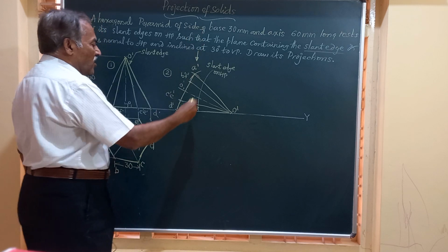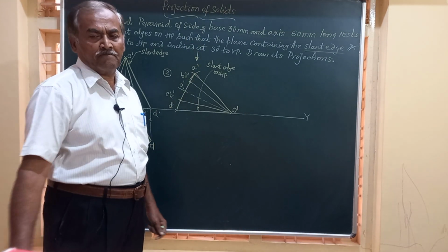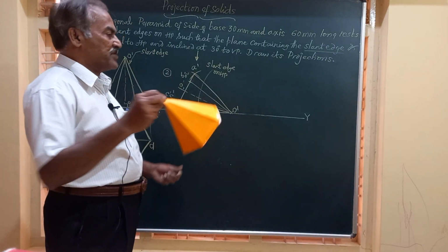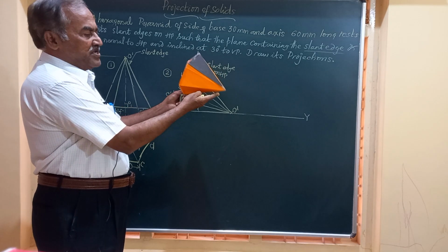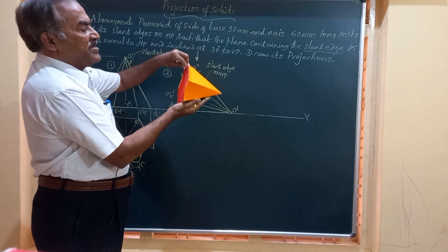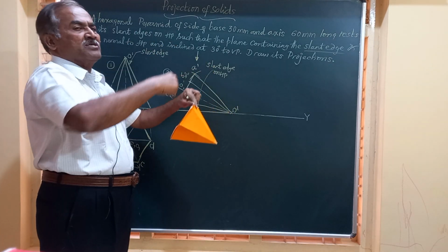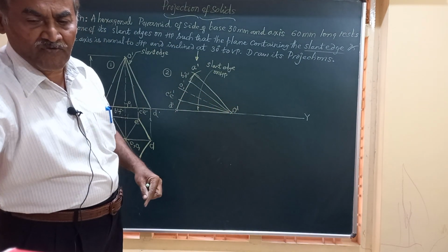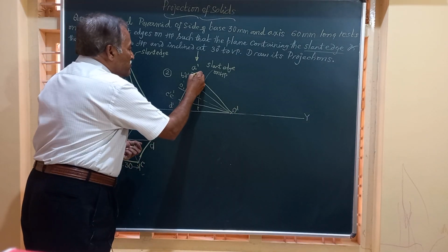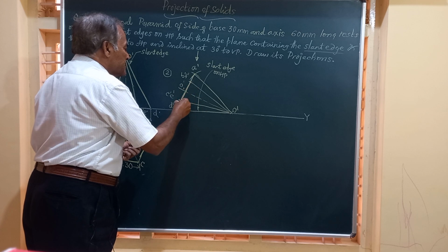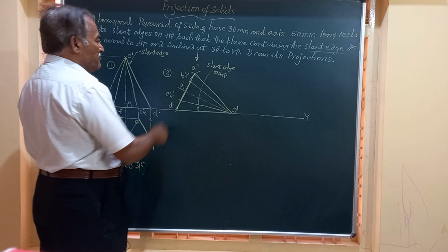and see how we view this solid. So friends, remember, whenever any of these pyramids rest on one of the slant edges on HP or one of the triangular faces on HP, the complete base of the solid is visible to the observer in the top view. So friends, based on this concept, I should be able to see all these 6 corners and also this line. So let us get the base first.